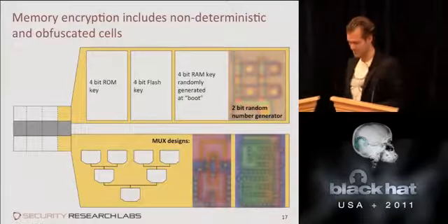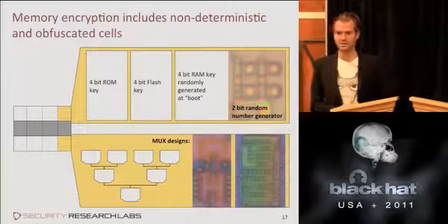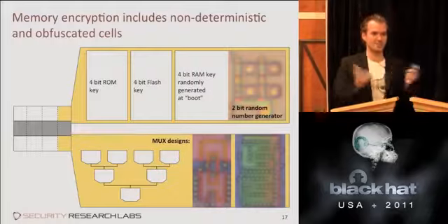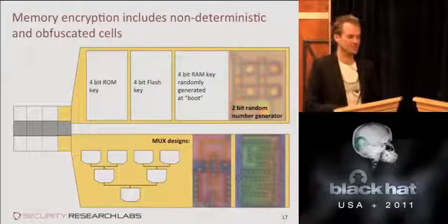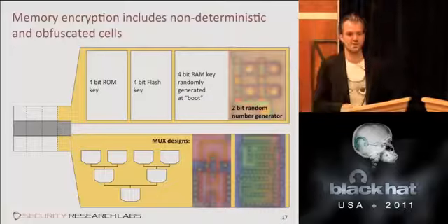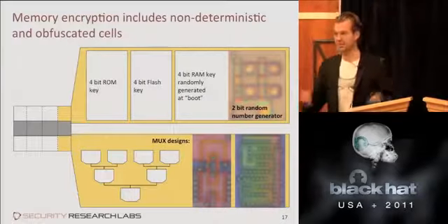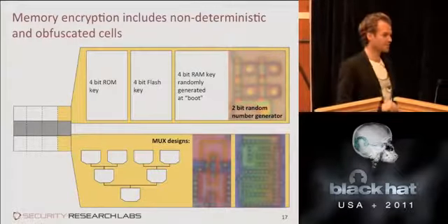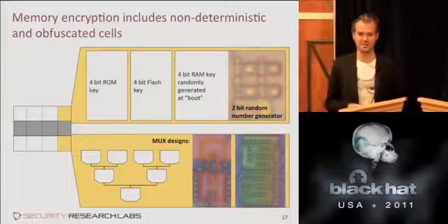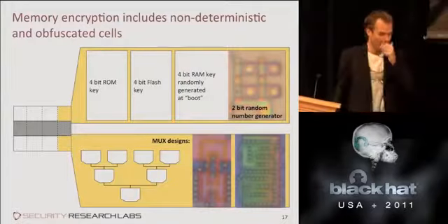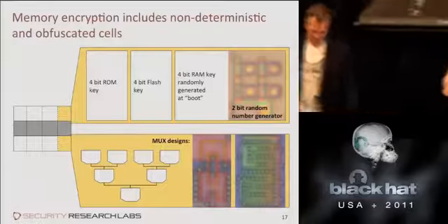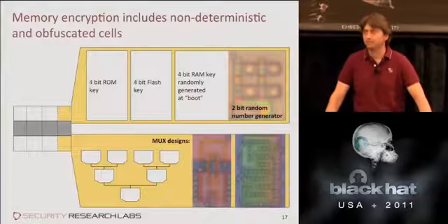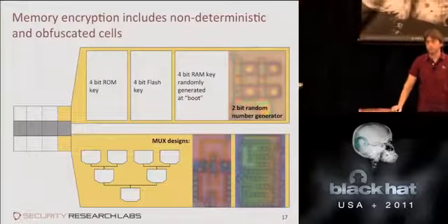Now that tells us, though, after we did it now, that there's really no level of obfuscation people can't get around, right? There's only so much you can do without breaking the functionality of the gates, and I think they try to push that border. So that's telling you, if you're interested in another chip, don't be afraid of obfuscation. In 90% of the cases, it will be much less obfuscation than this, and this has been done already now. Right. And in the smaller versions of this chip, those gates weren't so obfuscated. They made a lot more sense, at least when I polished it down. Yes, so in later versions of this chip, they took out some level of obfuscation.